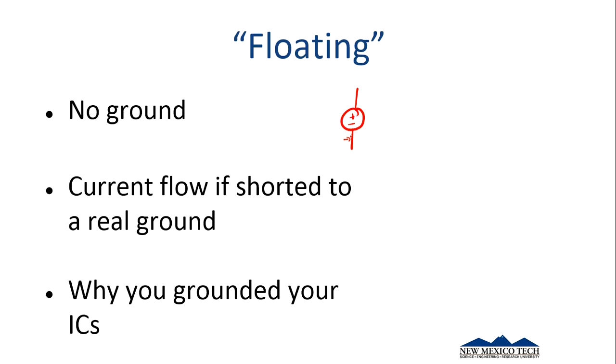But it could be that it isn't at 0 volts. It's only at 0 volts with respect to up here. So maybe we have some other piece of equipment over here, and if they get shorted together, we actually do get current flow through there. So that's what I mean by floating. It's just hanging out, not really at true 0.